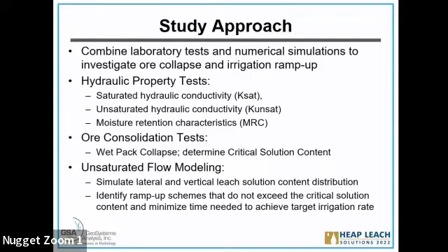We can simulate the solution distribution. I'll go over that a little bit later. And we also develop a crucial test. We call it the ore consolidation test, or the wet pack collapse test. So basically what we did, we use an agglomerated ore, and then we introduce pressure, and then gradually step up the solution content, and then see when the major collapse will occur.